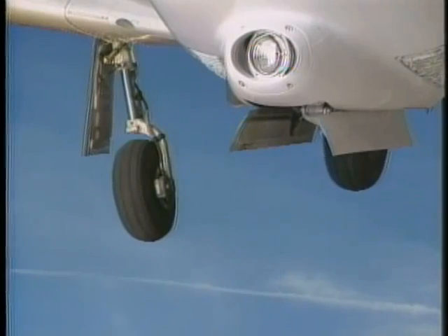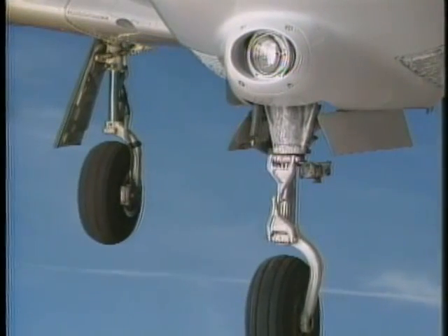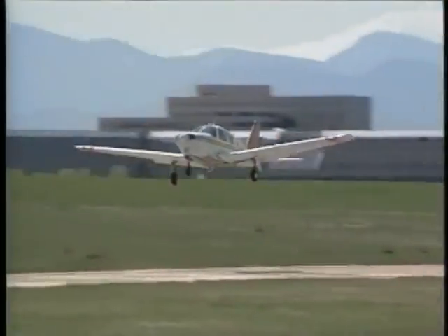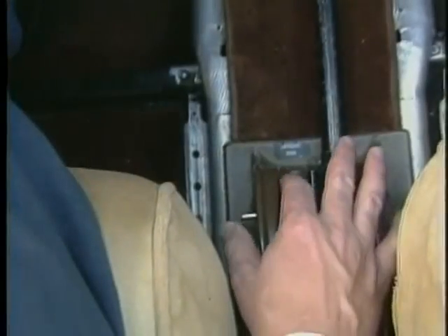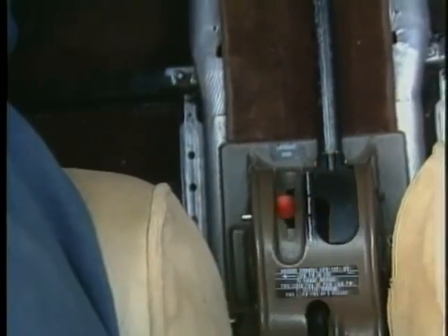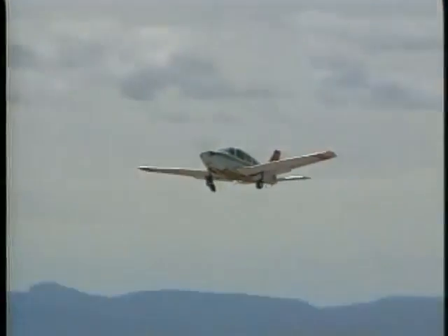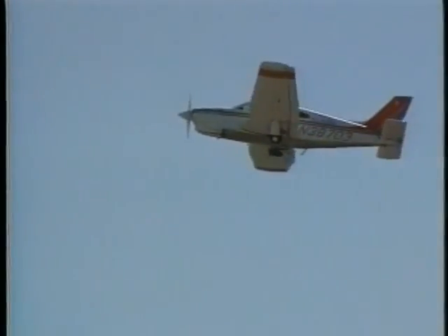The gear on some systems automatically extends when the airspeed drops below a designated value. This system also prevents the gear from retracting when below this airspeed. These auto-extension type safety features may be disarmed so the aircraft can be maneuvered with the gear up at slower speeds. For example, this system must be overridden in order to retract the gear during a maximum performance takeoff.